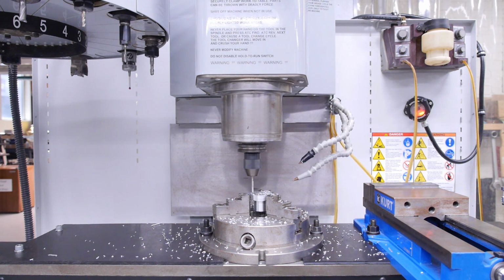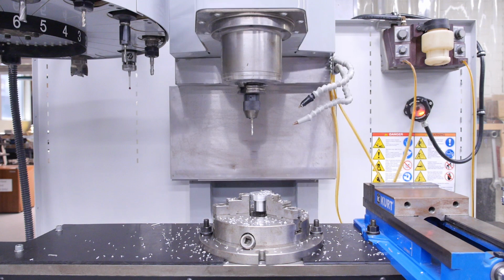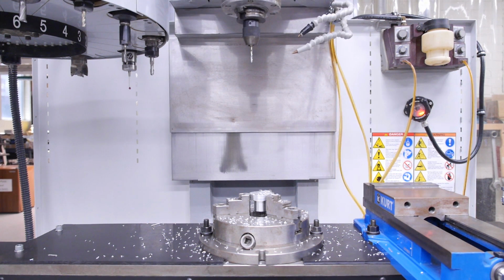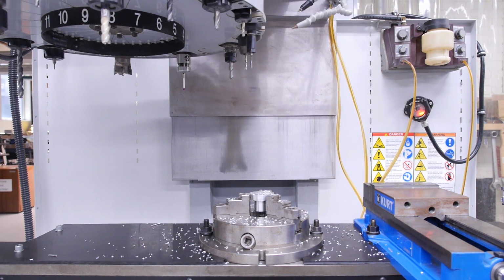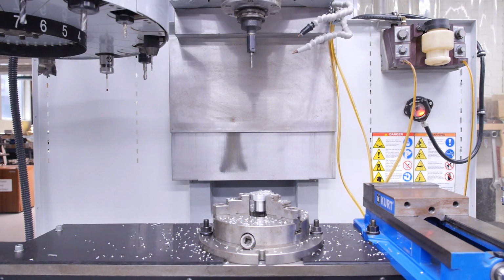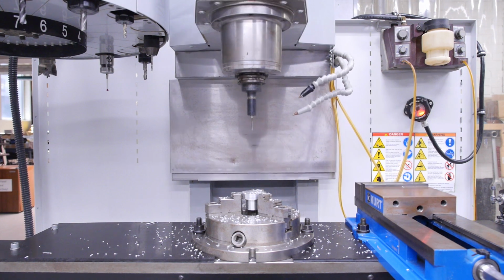When the tap drilling is complete, the CNC rapids the tap drill away from the part in preparation for a tool change and pauses while you answer any questions the students may have about this part of the program. Pressing the cycle start button initiates the tool change sequence, after which the CNC immediately rapids the tap to within 5 inches of the part surface.